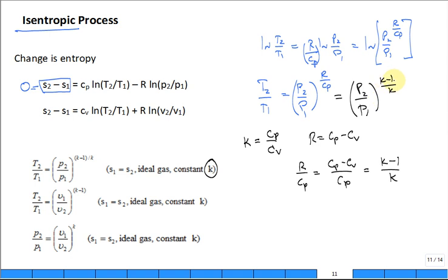At this point, we do have equation sheets, and you can say, I know how to rederive that, but in the interest of time, I'll just use the equation, knowing how to rederive it if needed. But we did a quick sketch of rederiving it. There are a couple of assumptions: it's an ideal gas, constant specific heats, and it's isentropic. How many people will use this for non-isentropic, in the vapor dome? I have to have an equation, so I grab one that looks like it'll work. You need to know when you can use it and when you can't.